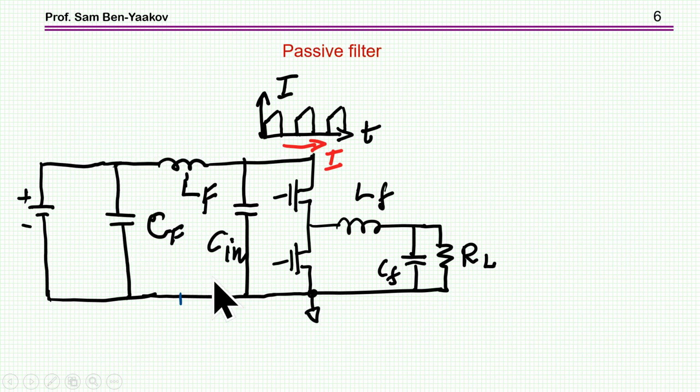So how do we solve the problem of attenuating these signals, the ripple, the noise? This could be by a passive network, like showing here, the capacitor. It's a pi network. And the idea is, of course, to block the current here and then have a high attenuation here. You might have another impedance here. So this is a passive approach.